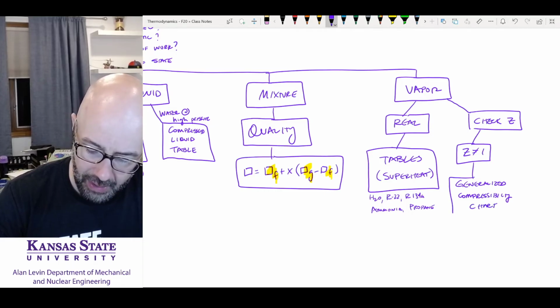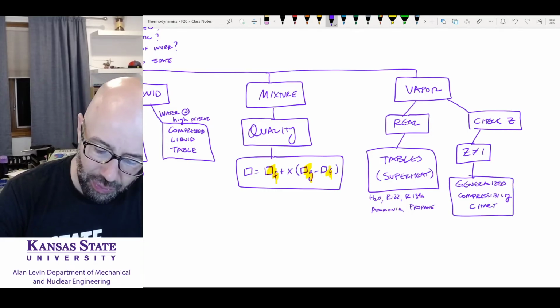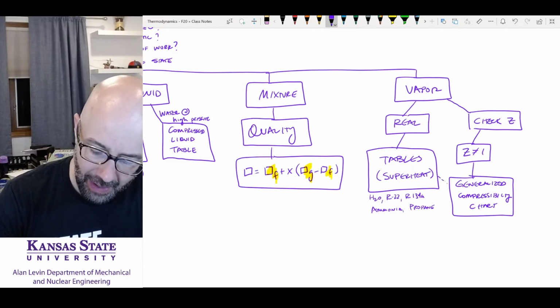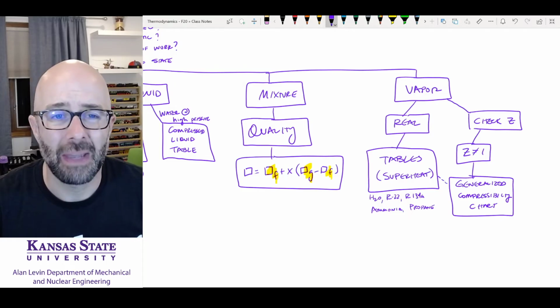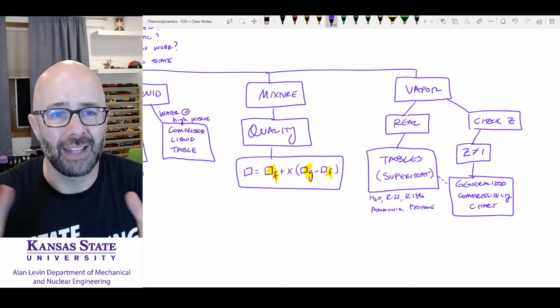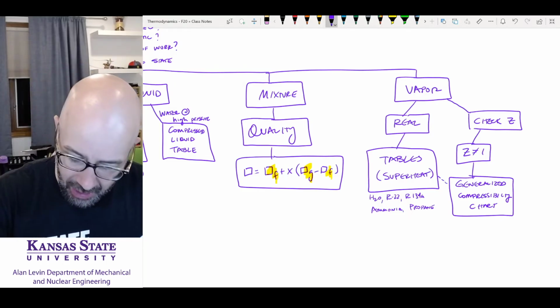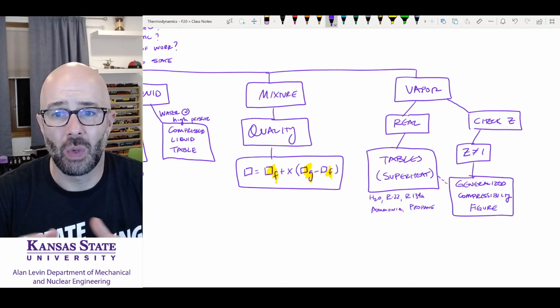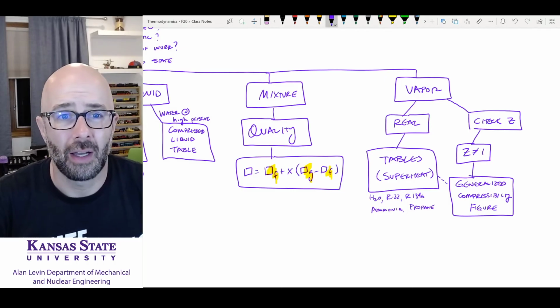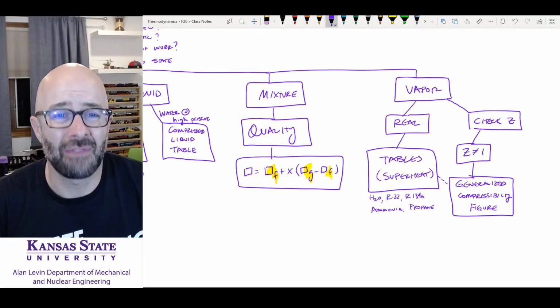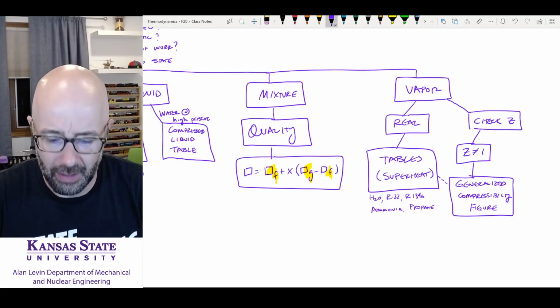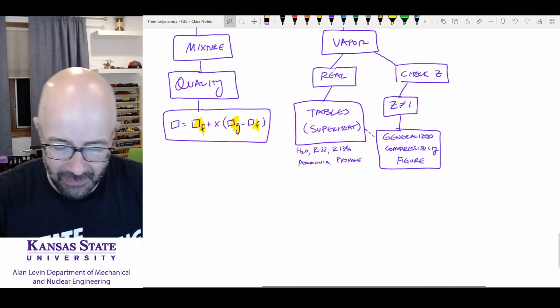I can just put a dashed line here. It's pretty close to what we have in our tables, but it's an approximation because we're using that chart, that figure, I should say. The generalized compressibility figure is a compact way of trying to use the tables. You should get the same values as the tables, but they're going to be a little off because we're using this figure.